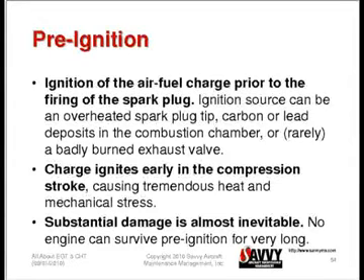Pre-ignition is a quite different phenomenon. Pre-ignition occurs when combustion starts at some time other than when the spark plug fires. In other words, it starts at an inappropriate time. And what will cause pre-ignition is anything in the combustion chamber that starts glowing red hot and can act as a glow plug, essentially, and start the fuel-air mixture burning without benefit of the spark plug going off. For example, we talked about the fact that detonation can cause damage to spark plug insulators. If the spark plug insulator fractures, then the spark plug can start acting like a glow plug, and can cause pre-ignition.